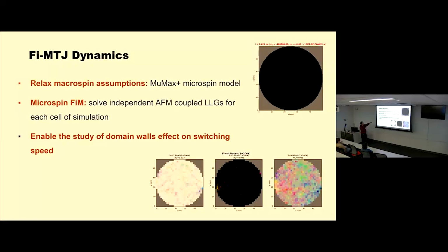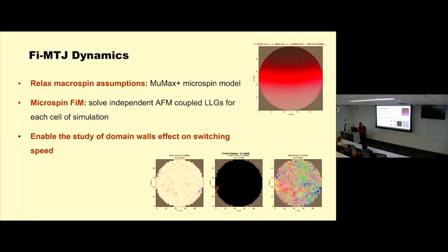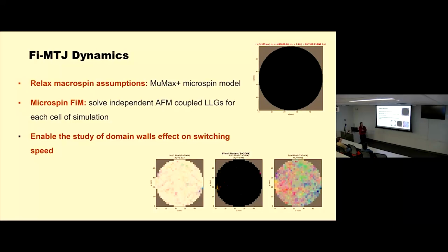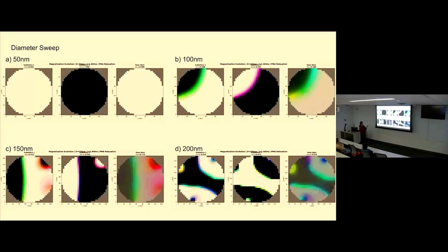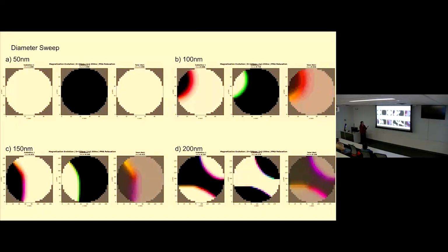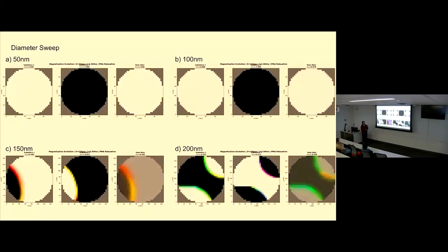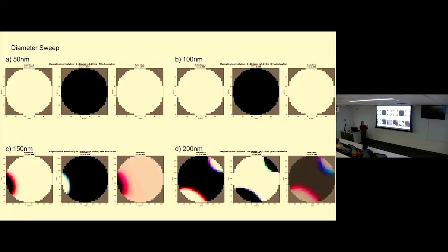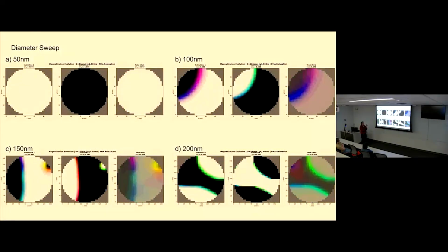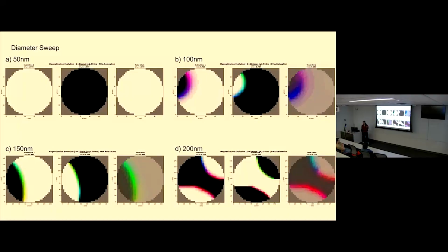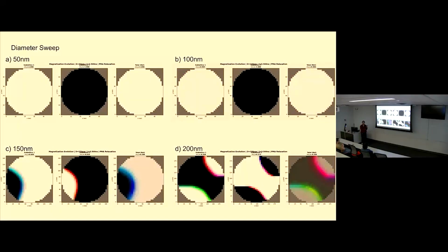And here, as we can see, even in this fast one, let's watch it reset. You can still see a domain wall forming there. I took this further by simulating a bunch of different sizes. As we increase the size, and this is what we expect from class, we see these domains forming. Crucially, whenever you have domains forming at these larger scales, you can notice that the device actually doesn't switch all the way, or if it does, it takes a very long time to do so.